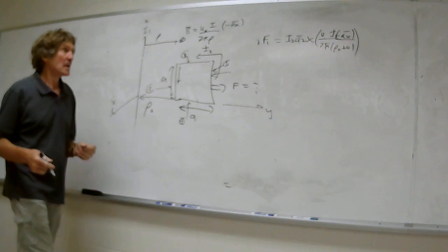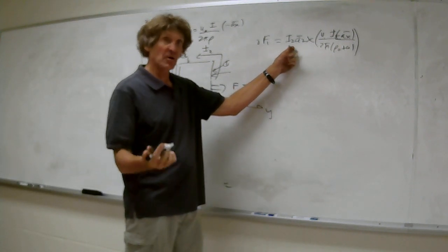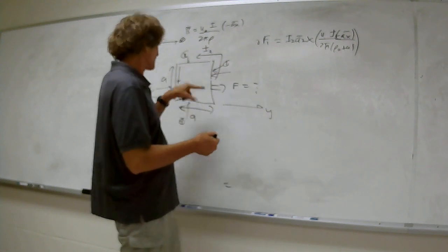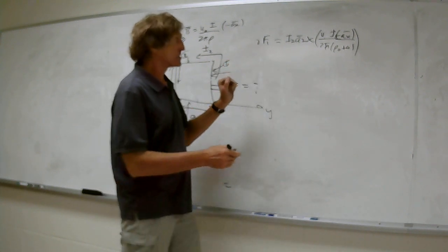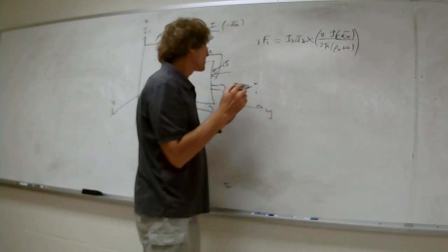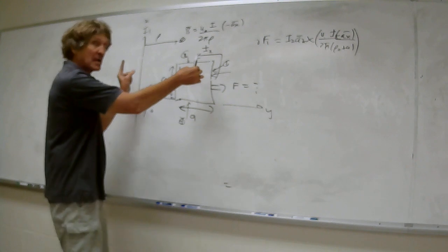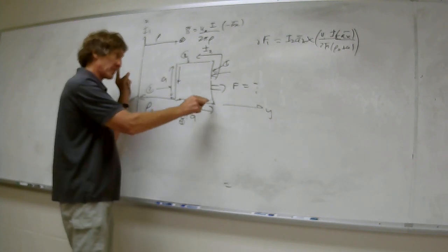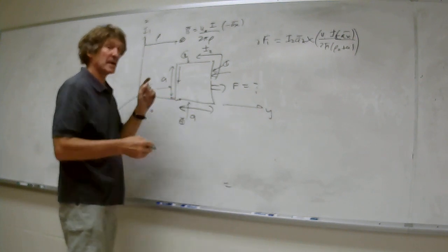All right. This is the differential force on this member. I2, because that's the current flowing there, is I2. I on purpose made it going counterclockwise. AZ, it's going the AZ direction there. You'll notice here, these two currents are in the same direction, right? This for this element right here. So we know they're going to pull together.